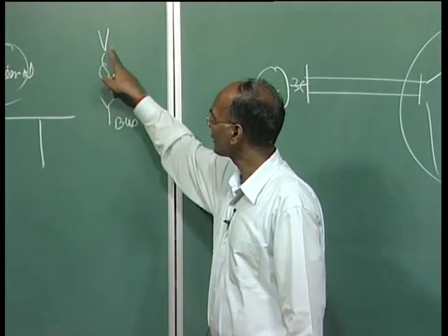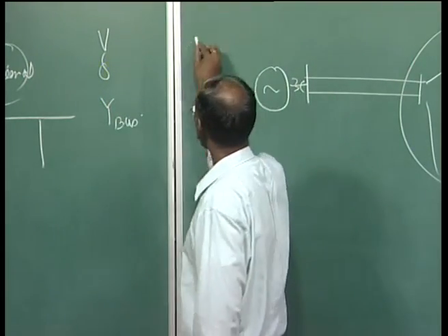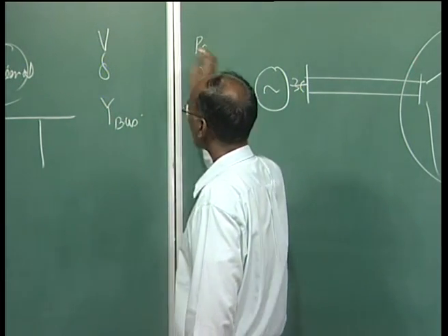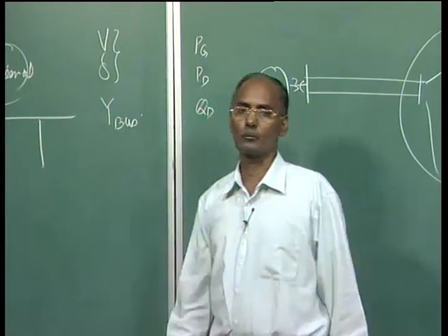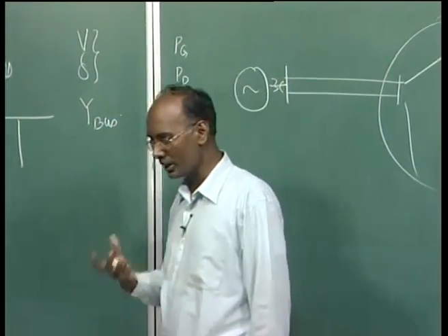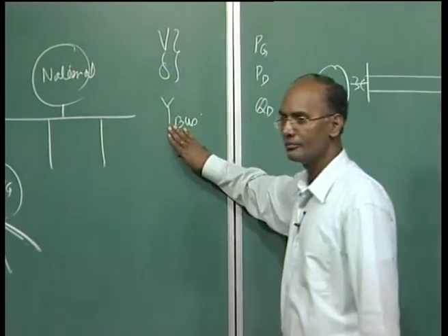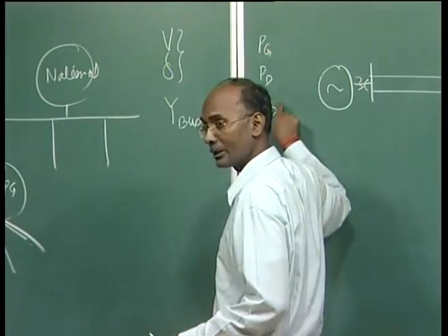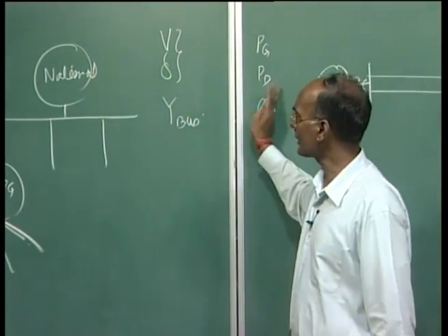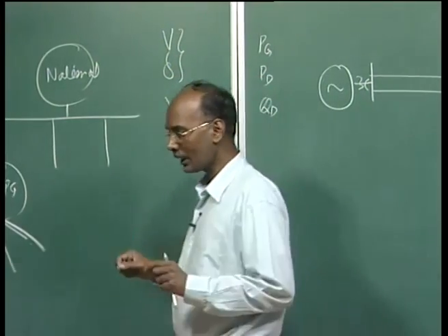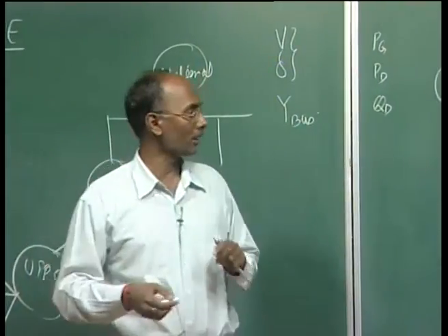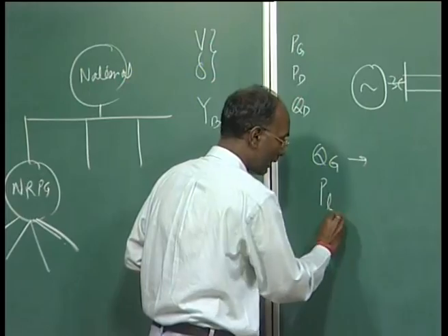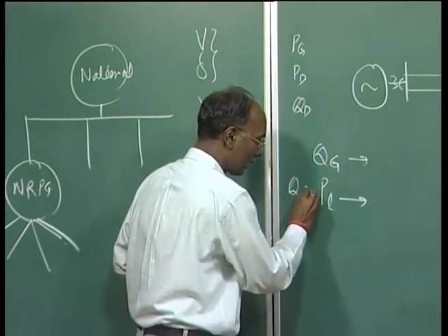So, here this is the Y bus you have, this is given to you. Then we require this V and angle based on your PGs, generations, your demand, your reactive power demand etc. Then we can calculate this in the load flow. So, we try to get the states based on the available information. The load is varying, these are the varying quantities, and this is a fixed quantity. Based on that we calculate voltage and angle, and once you have the voltage and angle, then you can calculate your reactive power generation, and you can calculate the line flows, both real and reactive.